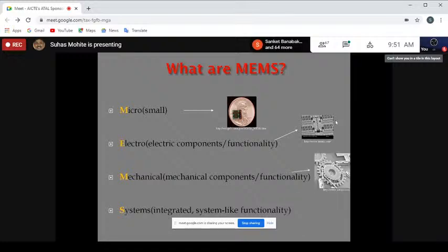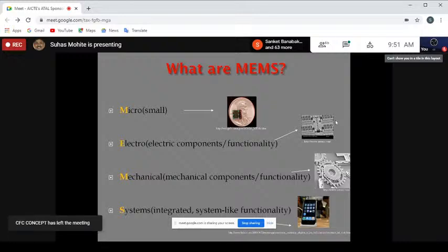So these are some of the marvelous creations. Friends, mind well that you are all currently using these MEMS devices, and these devices are very much sitting in your mobile phone, which you are carrying in your pockets. I don't know whether you have ever wondered how small the microphone and the micro speaker in your mobile phone are, and what is the technology that goes into manufacturing those microphones. Those are essentially MEMS microphones, which are produced on a large scale with batch fabrication technology using silicon micromachining. The speakers too are being manufactured with this technology. Then you have what is known as a rotation rate sensor.